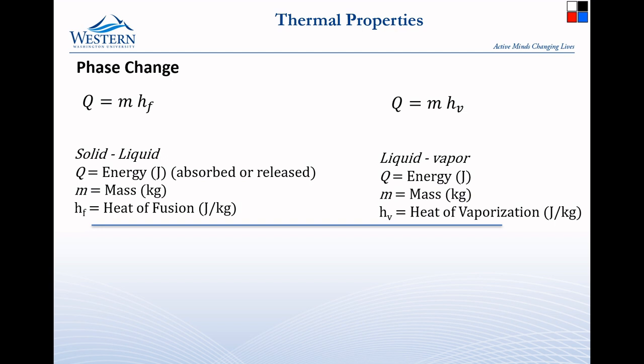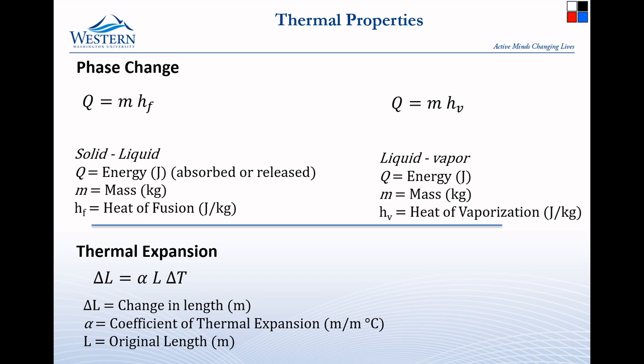Very often, when we take a material and heat it up to its melting point and then take it through its melting point, those amounts of energy will be the same order of magnitude. Not exactly the same. Usually heating it up to the melting point takes maybe 1.5 times as much energy, but order of magnitude, it is the same amount of energy just to melt the material as it is to do all of the work of getting it to the melting temperature, or to get it to the boiling temperature and then the amount of energy to boil it.